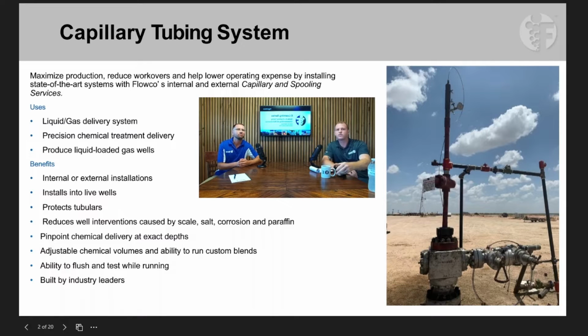Yeah, definitely. So those are the applications that we see, and we'll talk a lot more about whether it's CO2 injection, chemical injection, or foamer injection based off of the well type. But the idea is to either provide artificial lift to the well that may be different from ESP or rod pump or gas lift or plunger lift, right? Right. If they're using it for chemical injection, hopefully that chemical is protecting the tubing. Maybe it's keeping it from bridging off with salt. Right, which is mostly what you see in the Permian.